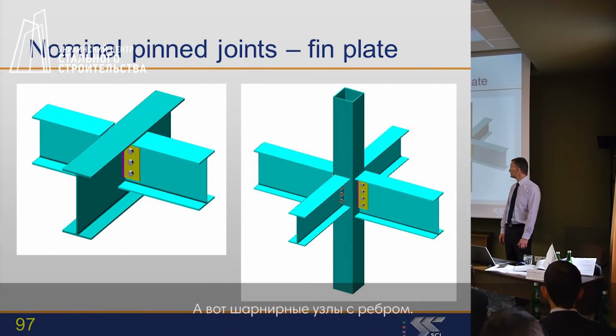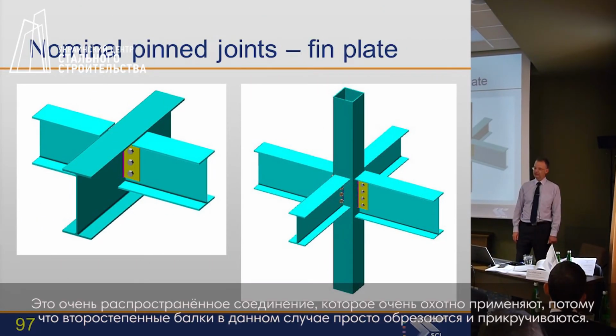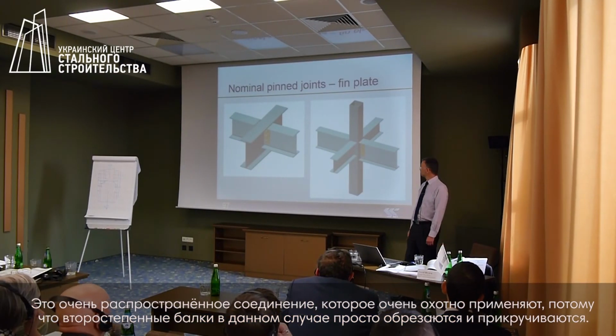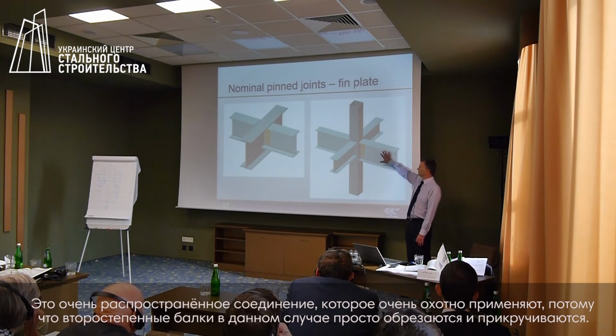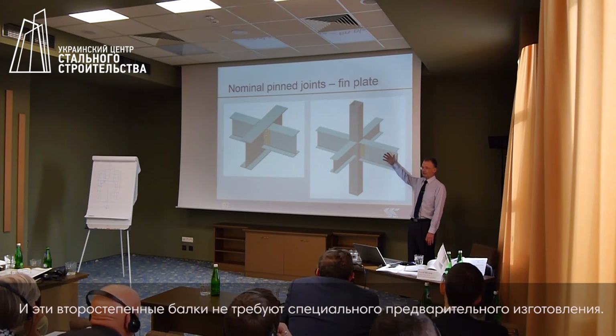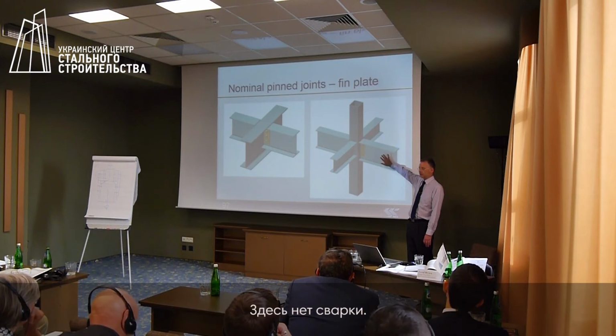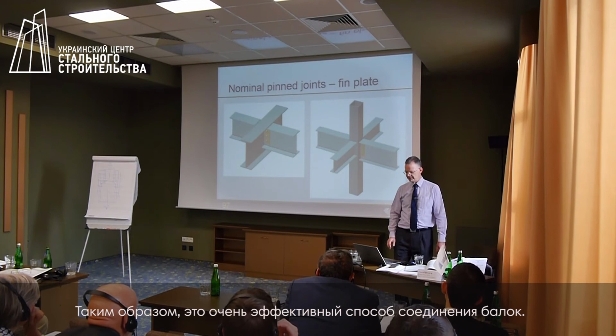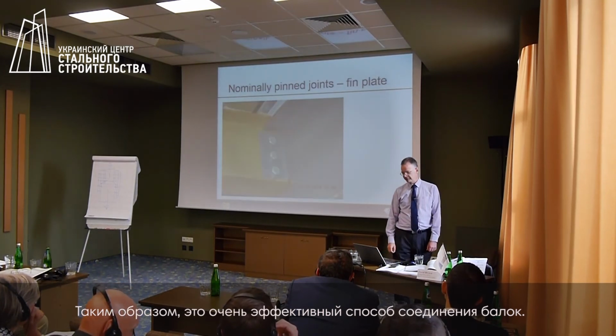Here are fin plates, a very, very common connection used with enthusiasm because the secondary beams have simply been cut and drilled. There is no fabrication of these secondary beams. There is no welding. So this is a very efficient way to arrange beams.